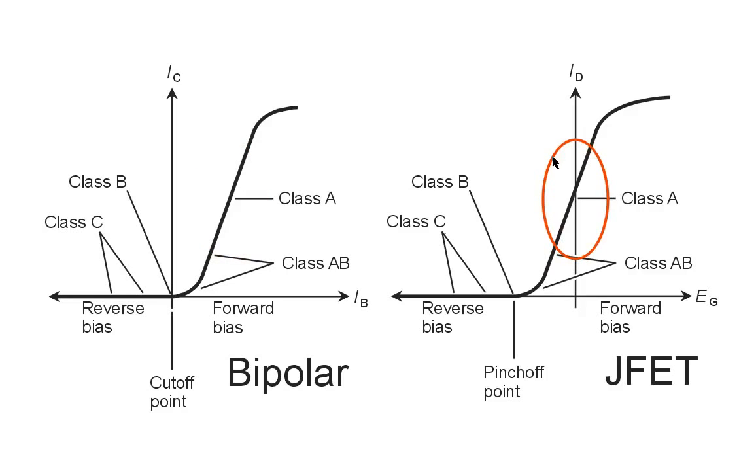However, when it comes to the modulation envelope on a radio frequency signal, we can get away with Class AB operation and we'll still get a linear reproduction of the modulation envelope. Even with Class B, we'll get a linear reproduction of an amplitude modulation envelope in a radio frequency power amplifier.